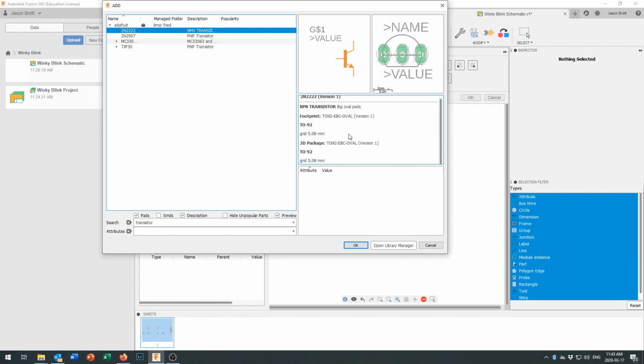All right, so here we go. We're going to hook this up, and Adafruit's been really good right in here. They've given it nice big oval pads so that when you drill it out and solder it together, it should go together fairly easily. There are other designs for an NPN transistor, and you can take a look and find them in different libraries. But some of them will put the base pin further back here and use round pads, which just gives you a little bit more space for soldering. Sometimes makes it a bit more difficult to route and insert the part. This looks like a great part.